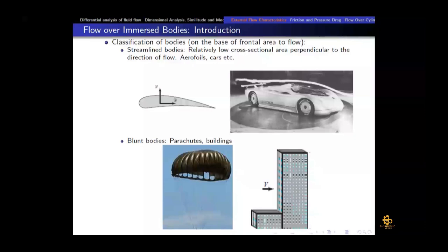So I hope that you understand this point, that there are two components of drag. Let me repeat. One is skin friction drag, and that is due to the wall shear stress on a streamlined body, right? And then pressure drag, which is dominant in the blunt bodies when there is a flow separation at the back end. So pressure at the stagnation is maximum, and at the back end there is flow separation, wake region, there is essentially the negative pressure. So that's why we would have a pressure differential at the frontal and back edge.